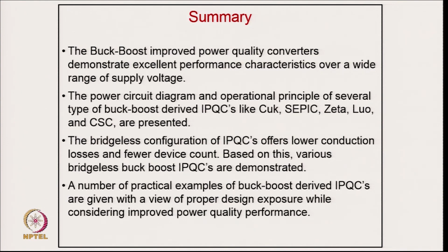With this, we would like to summarize. In the summary, the buck boost improved power quality converters demonstrate excellent performance characteristics over a wide range of supply voltage, with power factor correction as well as no reactive power burden. The power circuit diagrams and operational principles of several types of buck boost derived improved power quality converters like Cuk, SEPIC, Zeta, Luo and canonical switching converter are presented, and the bridgeless configuration of these improved power quality converters offers low conduction losses as well as fewer device count. Based on this, various bridgeless buck boost converters are also demonstrated.